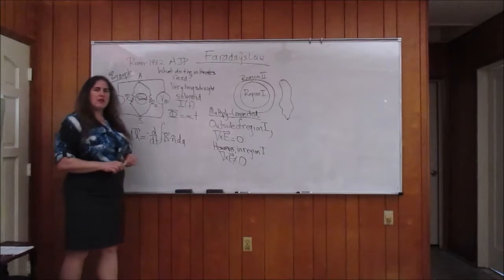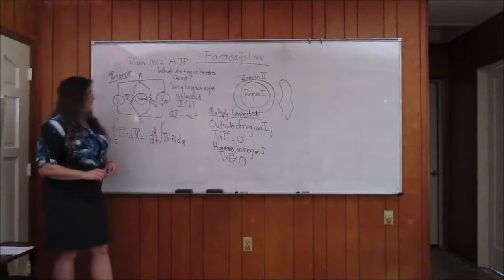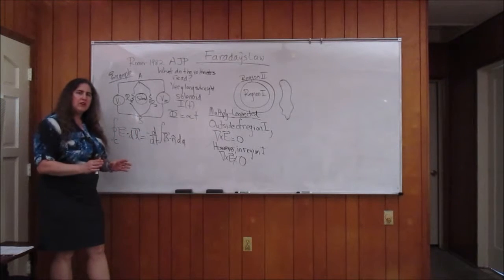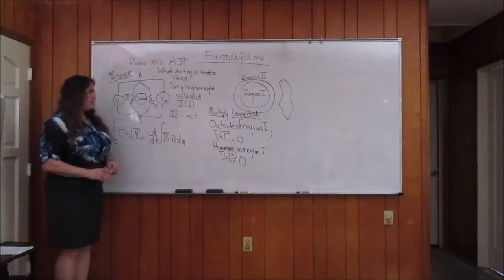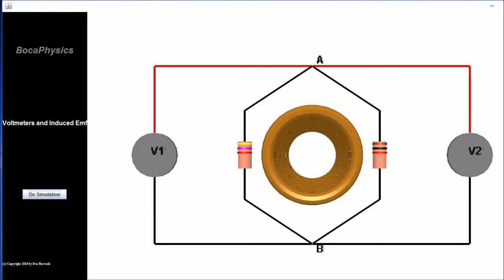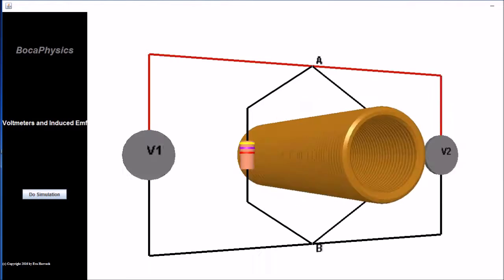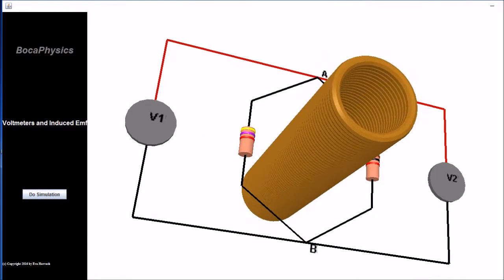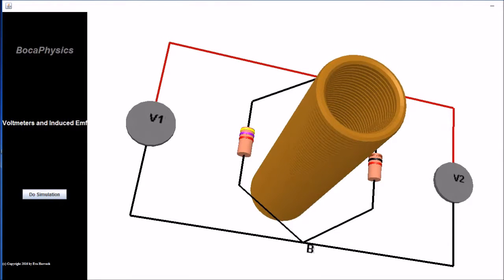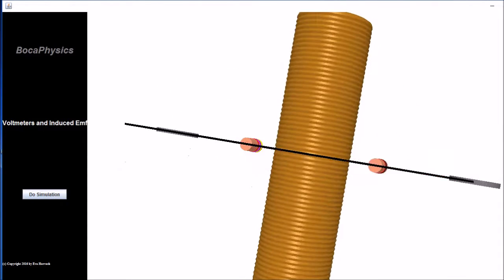Okay, let's take a look at a 3D simulation of this, just to drive home the fact that the topology of the circuit is important. Here we see a long solenoid that carries time-varying current. Along with the time-varying magnetic field, there must also be an induced electric field. For an infinitely long solenoid, textbook problems tell us that the magnetic field vanishes outside. However, for a finite-length cylinder, there certainly will be a non-vanishing small magnetic field. So as a practical matter, the resistor should be placed on the midplane of the solenoid.